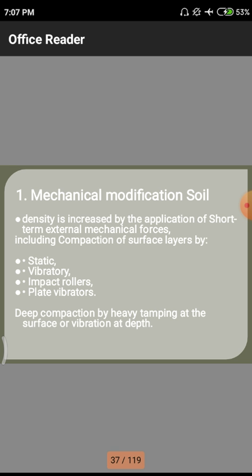Next one we are having plate vibrators. Plate vibrator means, normally in the concrete technology lab we are having these vibratory machines, so that we are having point vibrators and plate vibrators. Plate vibrators are mainly used to compact concrete at slab levels. Normally point vibrators are used in columns and beams like that. Plate vibrators are used in slab-like structures, the flat structures.